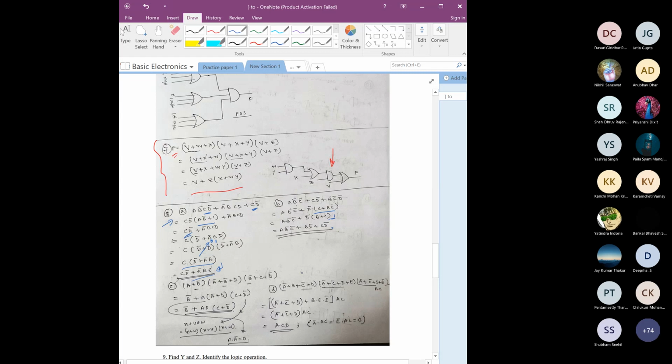That's one. Now here, this function is given in this fashion, right? In the POS form. So here you have to simplify it. What you can do: here this is B bar, right? You can take this B bar, and this part as an additional term, like this is B bar A and this is B bar, and this A bar plus D taken with a variable. So that way you can write it like this: B bar plus A into this A bar plus D, right?